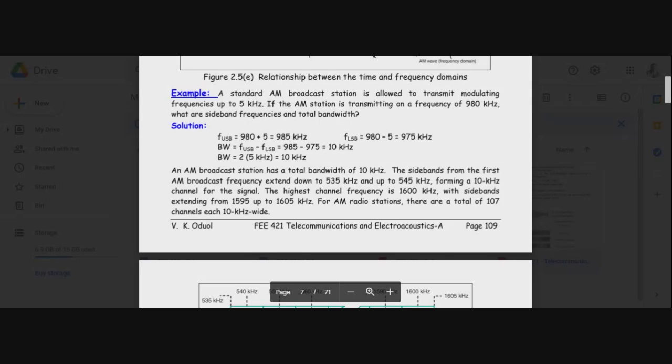And you see that when you try to do frequency translation, you take a 5 kilohertz tone and you translate its frequency, let's say by 100 kilohertz, you'll find that it's going to have two tones, and then you'll be wondering what happens. There will be one at 105, and there will be one at 95. So there's the shifting frequency plus or minus the message frequency. Okay.